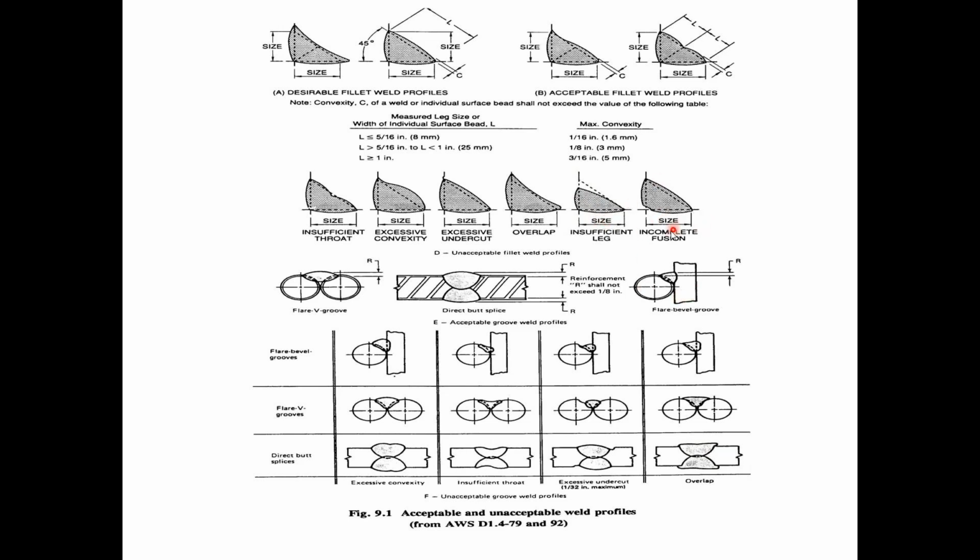This one, again, some of these are hard to illustrate, but you can see maybe the problem is illustrated here at the corner, the intersection of the two pieces of material, where you get this incomplete fusion, where the weld doesn't fully penetrate into the base materials all the way to the corner. So, these are illustrated with these other diagrams, but hopefully that helps you understand what some of the issues might be with these different weld types.